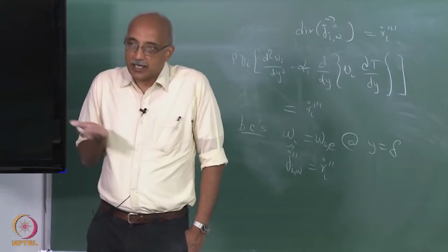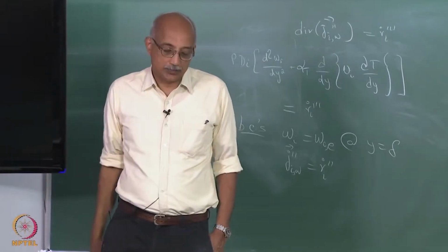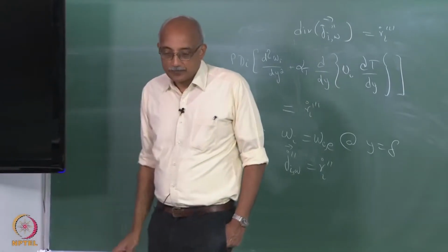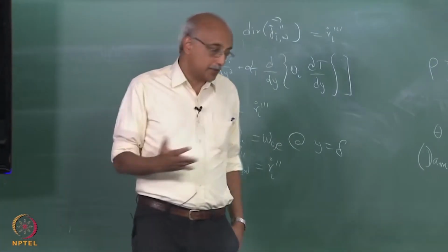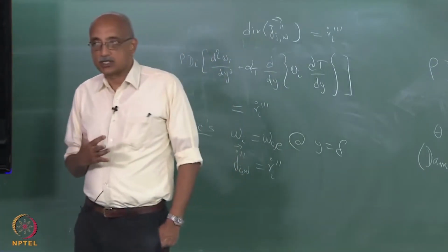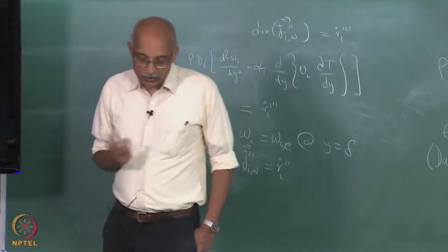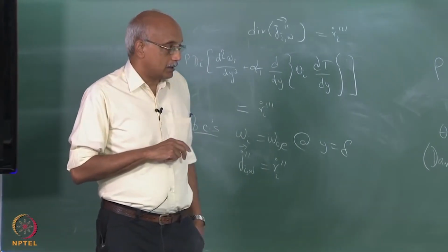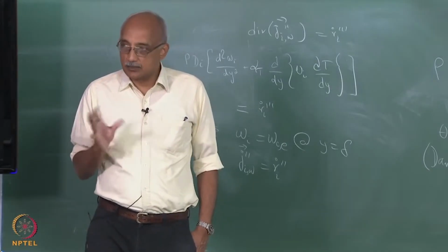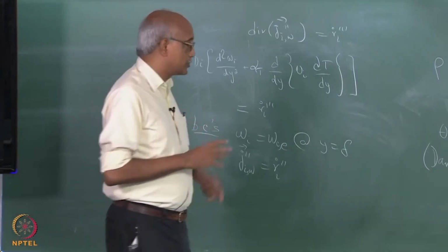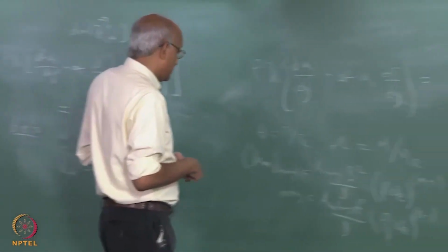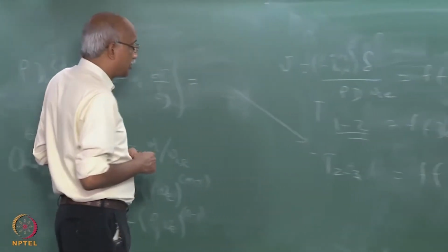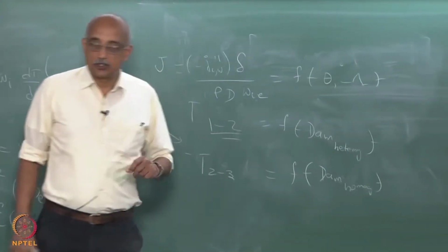You are kind of making the gas behave like a deposition substrate, but unless you do that, there is always going to be a higher barrier for gas phase nucleation compared to heterogeneous nucleation. And so, you can establish a condition which will be based upon the ratio of the Damköhler numbers for heterogeneous and homogeneous nucleation.